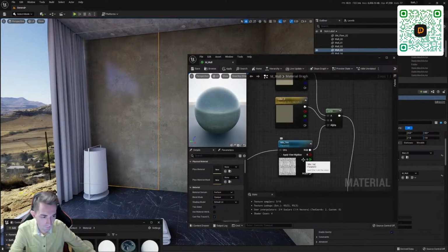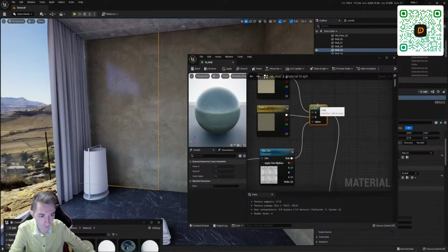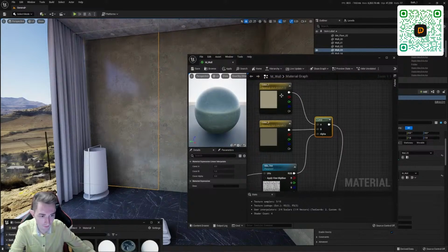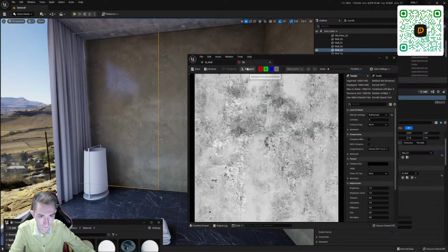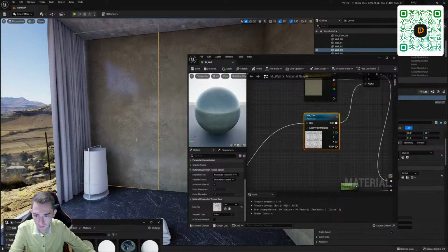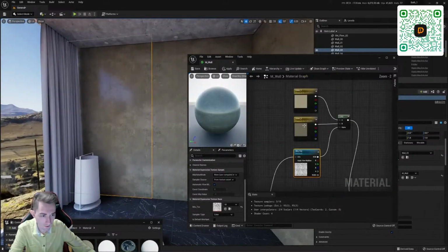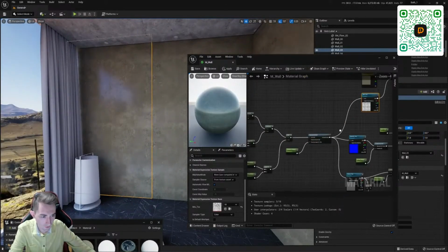I'll explain lerp in general. Lerp is such a node, like a mix in 3D Max, where we mix two channels according to some mask or texture. There's something like that here, only it's called lerp. We are mixing two textures on the map. The alpha map is my usual dirt map. I'm going to show it now. Here it is, the usual dirt map. I have roughly picked an interesting map, and two colors are mixed according to it.